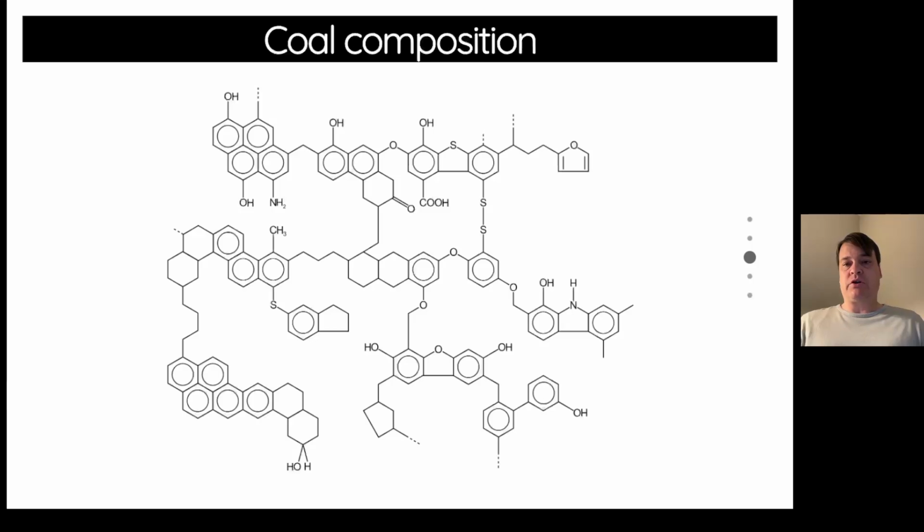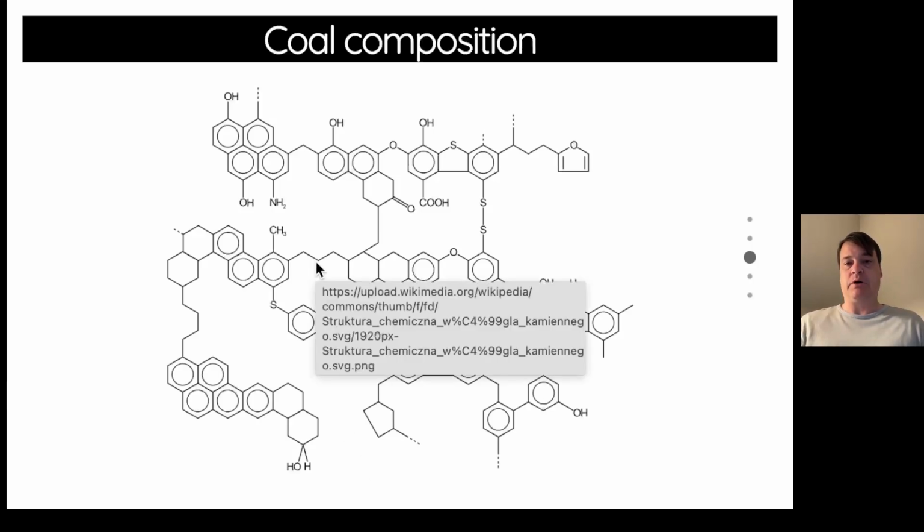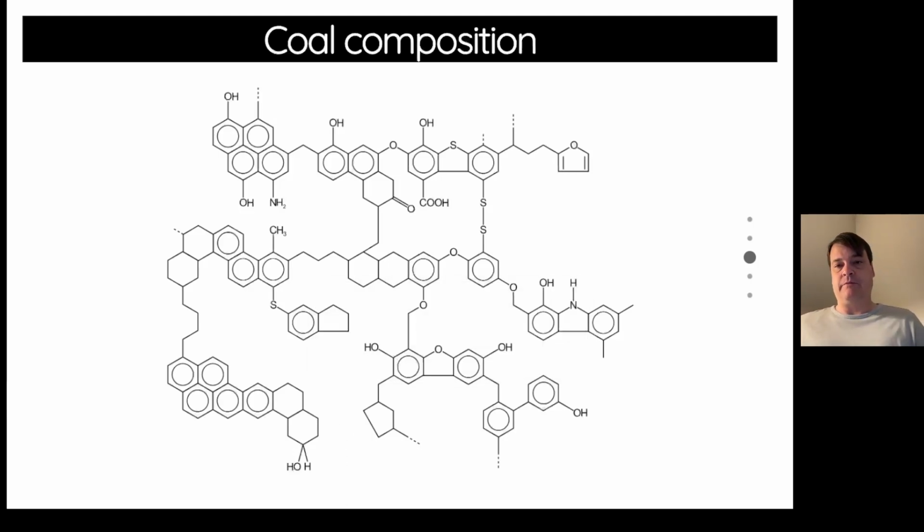As you heat this structure up, you get breakage along some of these bonds, and that results in volatilization of the coal. So when it gets hot, it releases gases, and those gases are what combust in the flames, leaving behind a carbon matrix that we call char, and that char then burns as a solid phase with oxygen diffusing to the solid to react and burn out the remainder of the fuel.